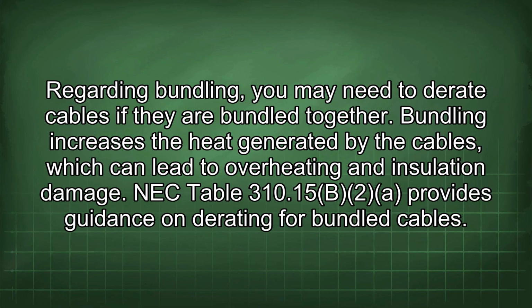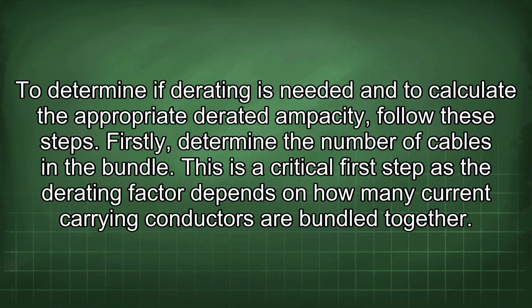Regarding bundling, you may need to derate cables if they are bundled together. Bundling increases the heat generated by the cables, which can lead to overheating and insulation damage. NEC Table 310.15(B)(2) provides guidance on derating for bundled cables. To determine if derating is needed and to calculate the appropriate derated ampacity, follow these steps.